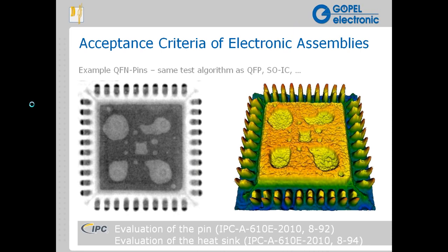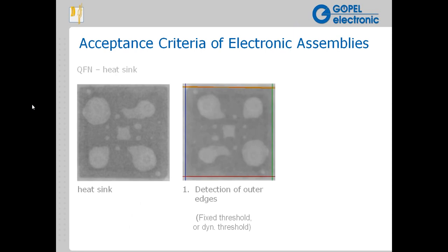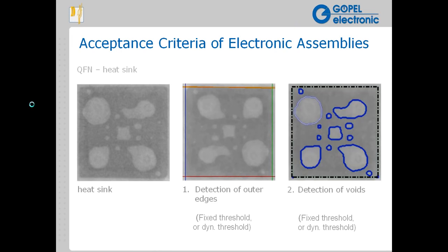Again, taking a little bit closer look at the verification station here. On the left is the visualization station that shows us the schematic view and the location of a particular failure. On the right image, we see the X-ray image itself. In this particular case, it is a package also soldered down to a heat sink. So you can see voids in the heat sink, and you can also see the solder joints on the pins. That is visualized very clearly in the topo view image on the right. And then there is a classification keyboard, a specialized keyboard that helps the operator or programmer classify failures as they come off.